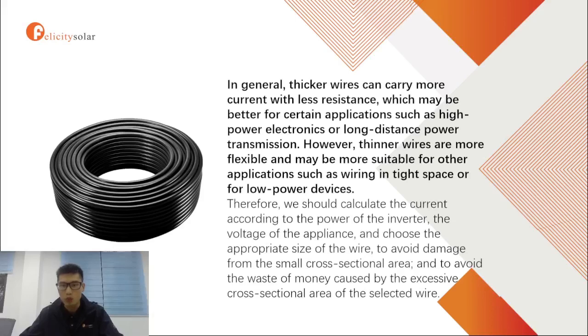Therefore, we should do the calculation first. We need to know the current, according to the power of the inverter and the voltage of the appliance, and then we choose the right size of wire to avoid the damage caused by a small cross-sectional area, or to avoid wasting money, because the thicker the wire, the higher the price.